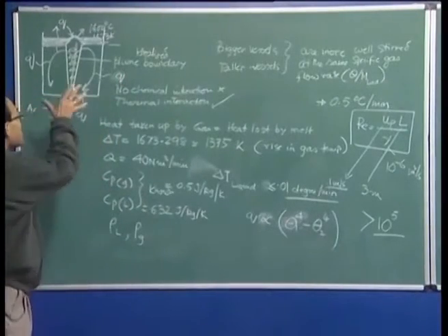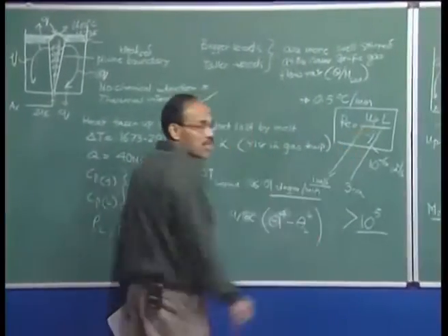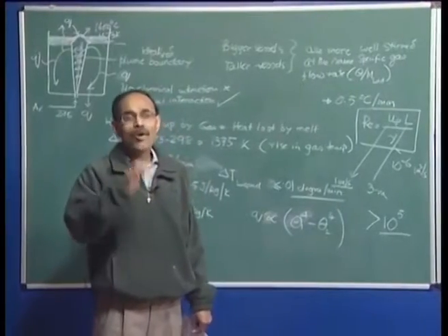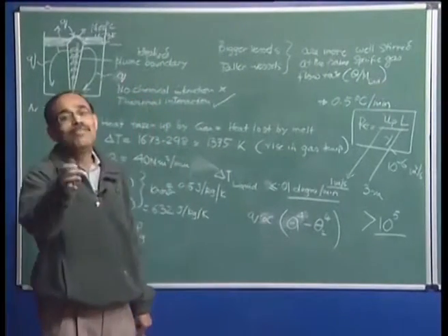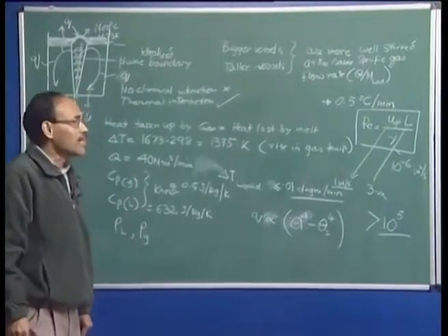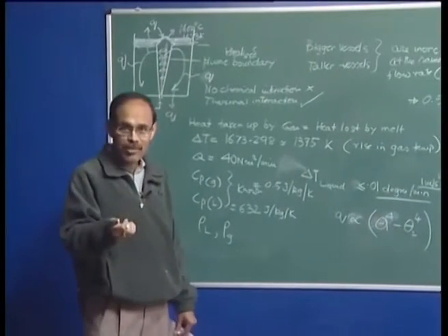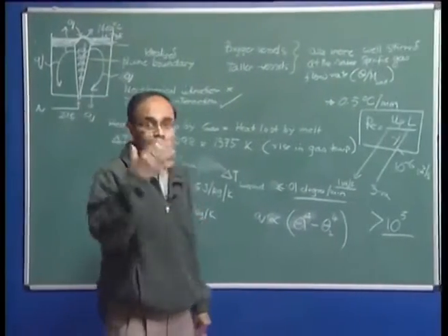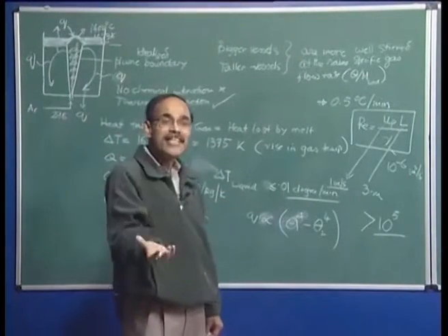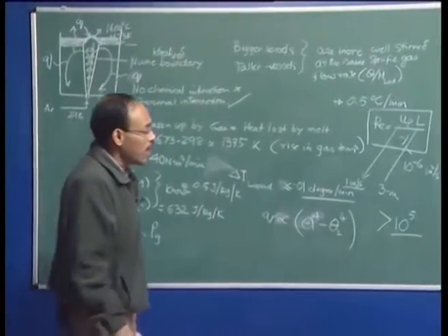Okay. So, given the large size of the steel processing vessel, the smaller kinematic viscosity of steel precludes low Reynolds number or laminar flows. It is an important understanding at this stage that in most steelmaking vessels, the fluid flow or molten steel motion that we are going to see is basically turbulent, and as we know, turbulence aids in heat and mass transfer. If there is more turbulence, fluids can jump from one point to another, and along with them they can take heat and mass, and therefore aid in more mass transport and heat transport.